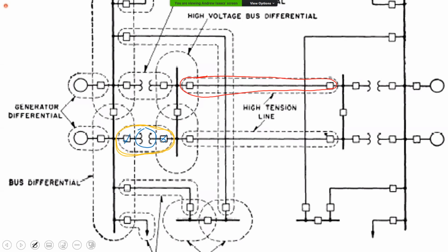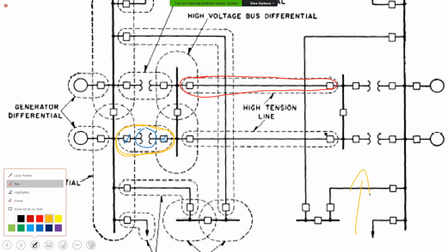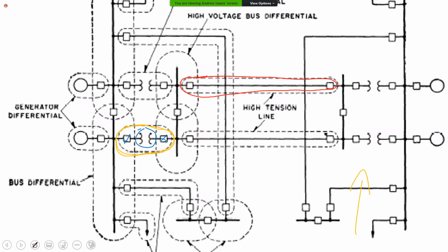All right. So I'm going to look on this side. And since the zones aren't shown over there, I'll just put it in. So again, here is my generator. Here's the breaker that's associated with the generator. So this zone would go through here. So it would include the switch gear, which would be the breaker, and it goes through the relay. So it goes beyond it.